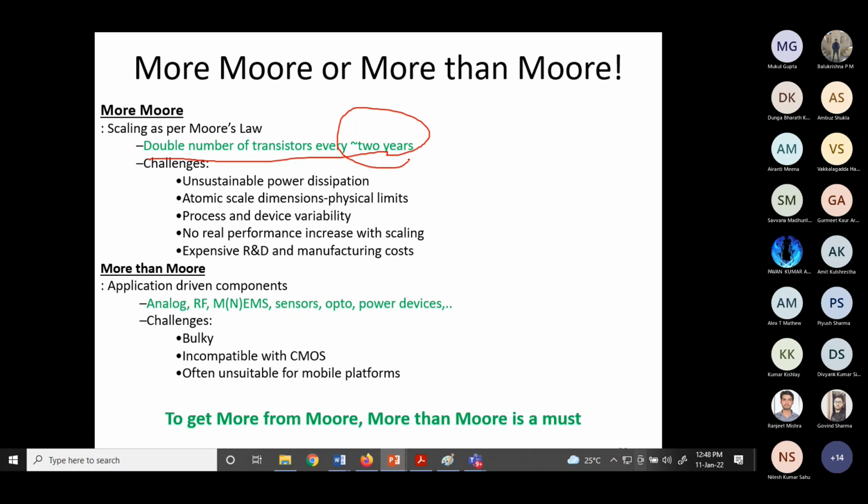That's very good actually. So all these advantages we can get, and there are a lot of challenges. We have discussed some of the challenges and how we can improve things, that also we have discussed a little bit. But if I jot down some of the challenges, you see unsustainable power dissipation, huge power dissipation in a tiny area, the temperature will be enormous, okay, of that small tiny chip. Your nowadays very hi-fi state of the art processors, you need some kind of cooling arrangement, whether you use a fan or some other technique, you need that, right?